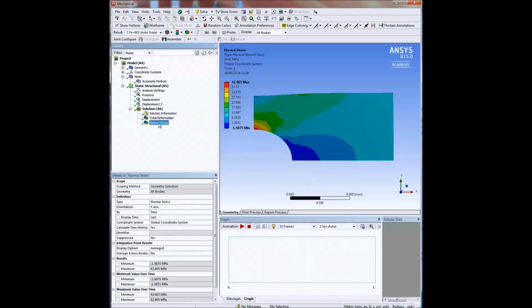And if we look at the stress, then the stress is what we would expect, and we're getting a high stress in the x direction at that point there due to the stress raising effect of the hole, and we can see the hole's elongated. So that has successfully analysed this plate with a central hole.